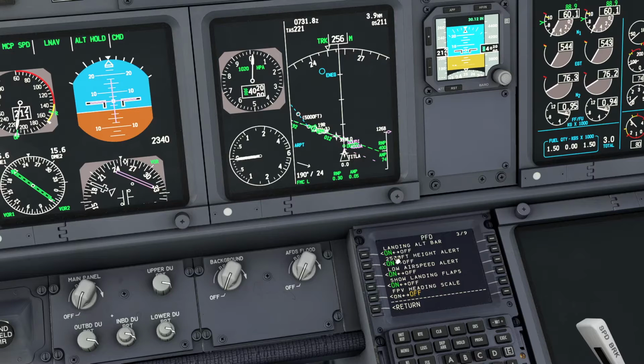Okay, so this 2,500 feet alert height, I just understood based on the documents, is the out indication that I just removed from there if you give them the off option. If you have the on option, it will show out here to give you an awareness that you are below 2,500 feet high. Okay, until you are 500 feet high.